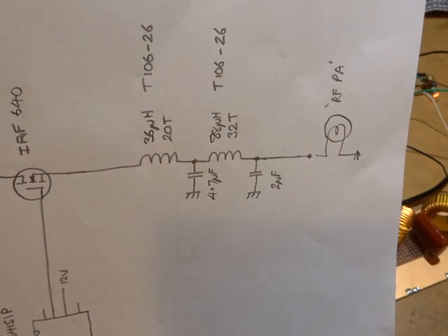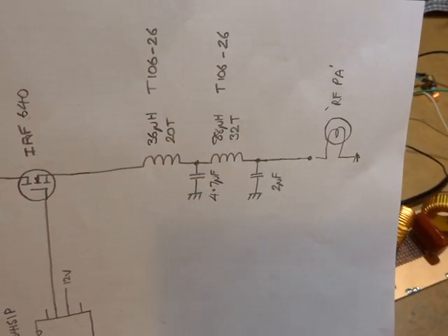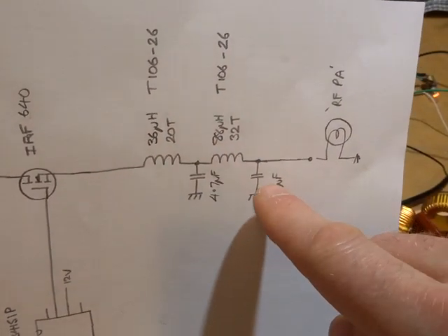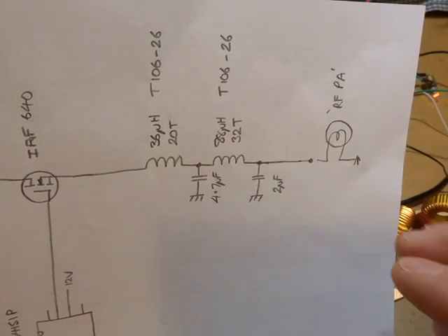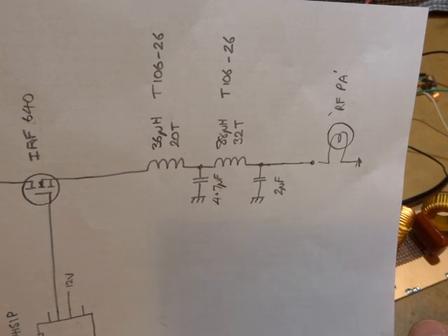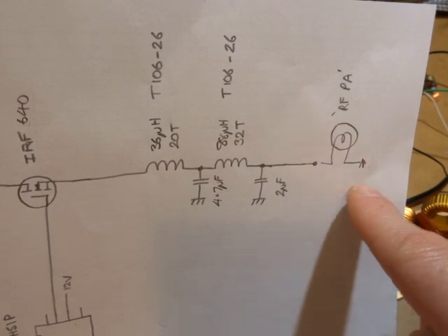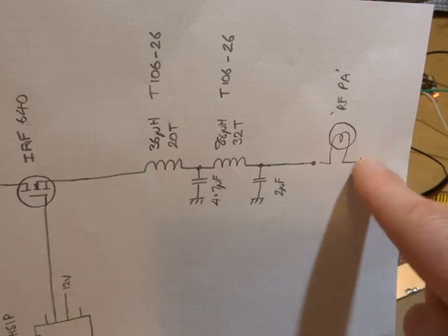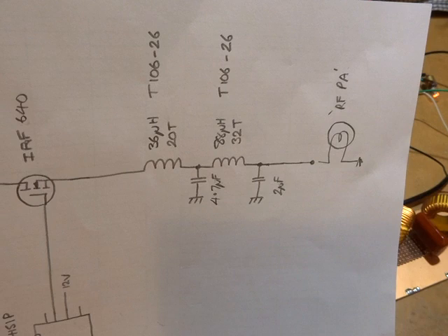Now, in terms of the parameters for setting up that filter, by all accounts from reading the literature, the cutoff frequency for that filter needs to be somewhere between 10 and 12 kilohertz. I elected to use 10 kilohertz, and for the termination impedances, I'm going to use a bit of a steer from Stephen's paper, where he's assuming somewhere between 6 and 8 ohms, so I used 6 ohms.